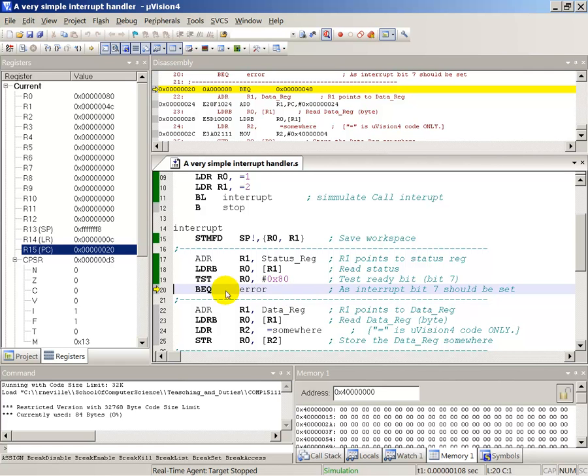And this bit of code here is just to say, well, it's taken the view that polling, the CPU controlled the process, so it wasn't an error. But in this case, as it's a peripheral, the peripheral has interrupted the CPU, so we're checking the status register. The bit should be set. If it's not, there is an error.